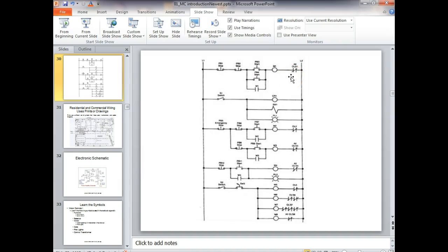Like I said, here we got some control devices in series. Here we got some control devices in parallel. This control device is series, but the load, this is a series circuit, because we got one load. Now what's nice about this is we're only going to deal with one load in series circuits. In line diagrams, we never have more than one series load. Never, never. We can have a lot of parallels, but we only have one series load. So all our series circuits are going to be one load circuits.